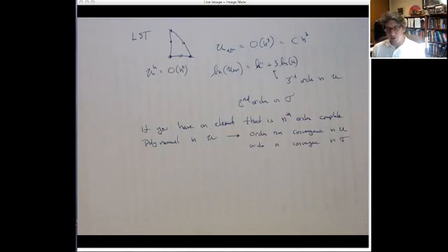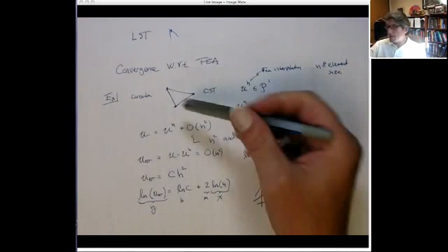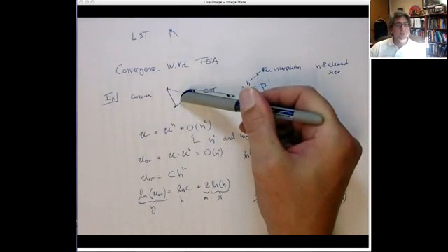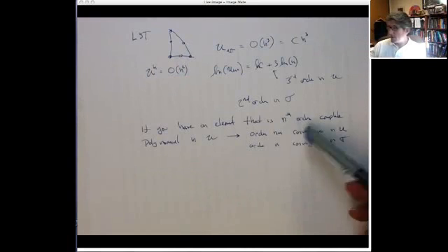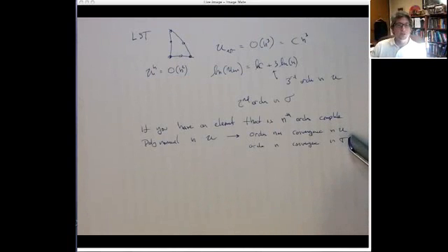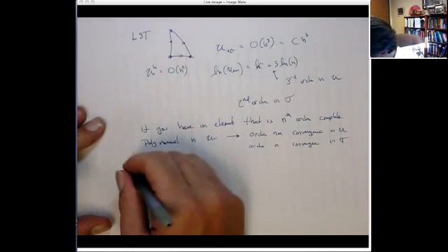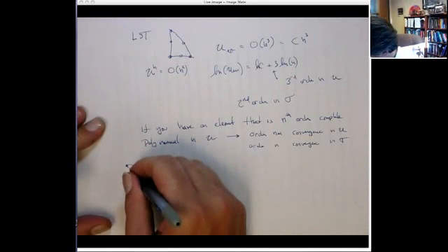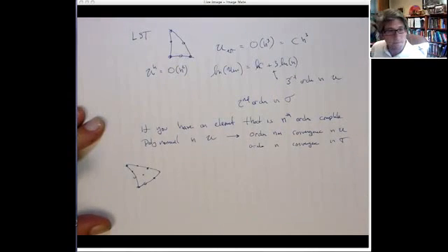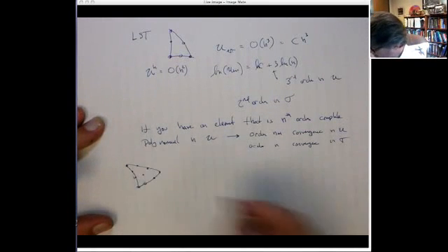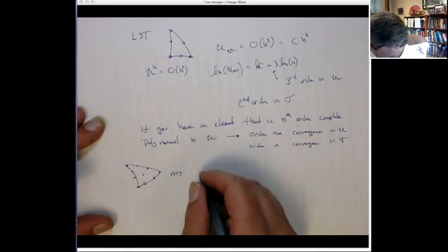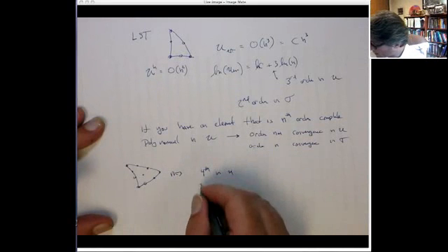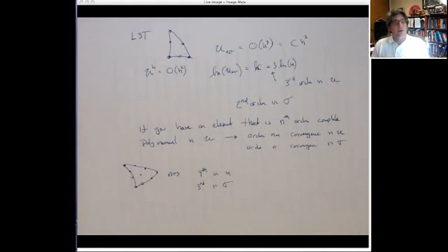So, right, constant strain triangle is linear. It's a linearly complete approximation for U. So that's n is equal to 1. So here, the convergence in U is going to be 2, and the convergence in stress is going to be 1, or first order. All right. So if you had the next highest order element, which is the cubic element, this is cubically complete, so n is equal to 3. So that means that it's going to be fourth order in the displacement and third order in the stress convergence. Okay?